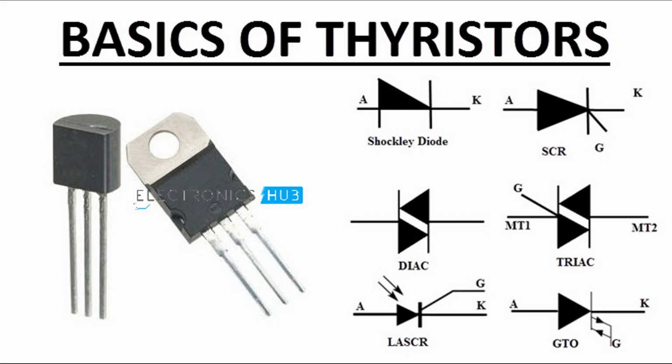Understanding the operation and characteristics of IGCTs is essential for designing high-power electronic systems that require reliable and efficient switching, making them valuable components in various industrial and power transmission applications. The MOS-controlled Thyristor, MCT, is a type of thyristor that combines the features of a conventional thyristor with the control capabilities of a metal oxide semiconductor field effect transistor, MOSFET. This hybrid device offers advantages in terms of control and switching performance, making it suitable for high-power and high-speed applications.